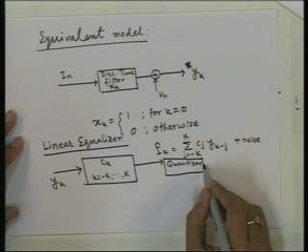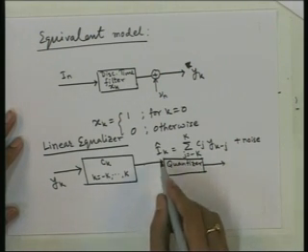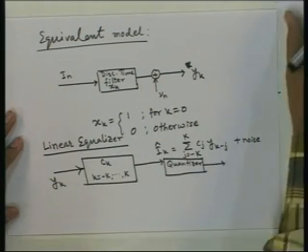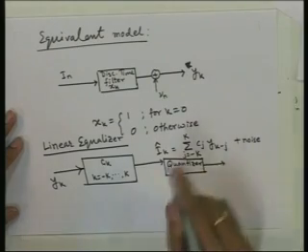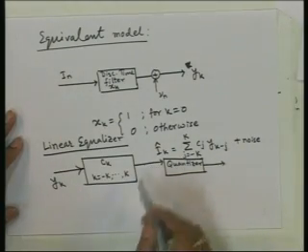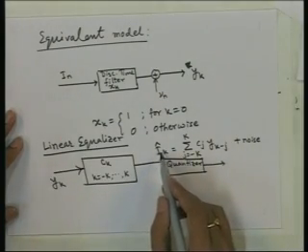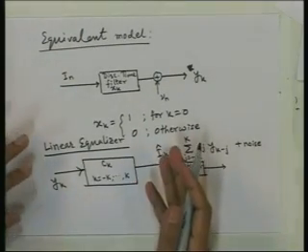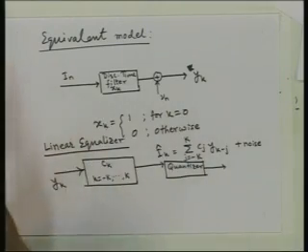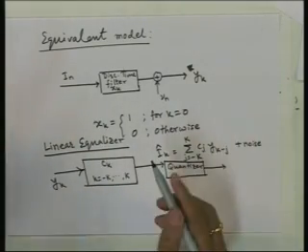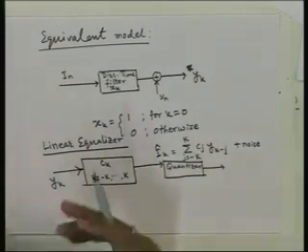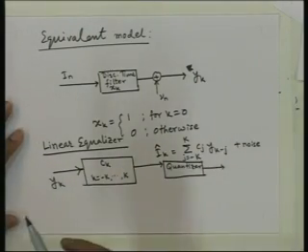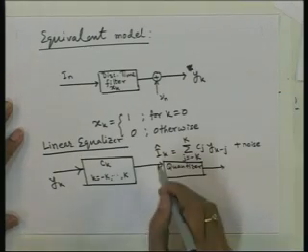So, what does this quantizer do? This is an estimate of the value transmitted, the value transmitted in I n. The value of I k is an estimate of that, but I n was actually a value picked from a constellation. If it is a real value, it will possibly be from a PAM constellation, or if it is complex valued, it may be a 2-dimensional constellation from where it was chosen. So, the quantizer will pick the nearest constellation point from I k.